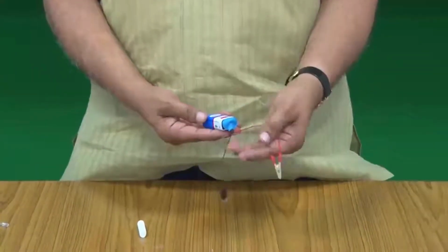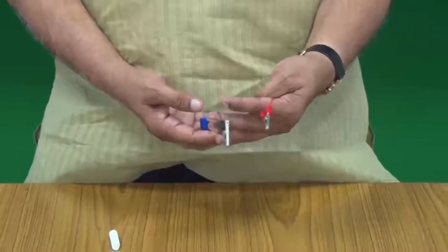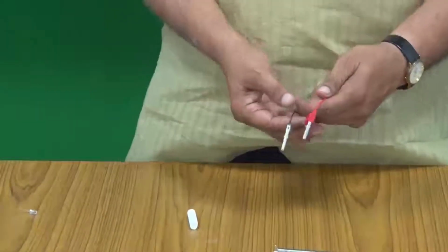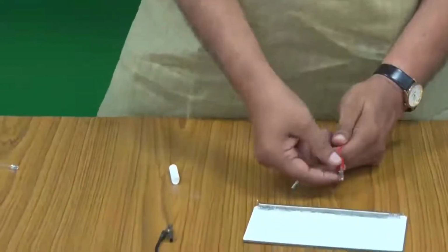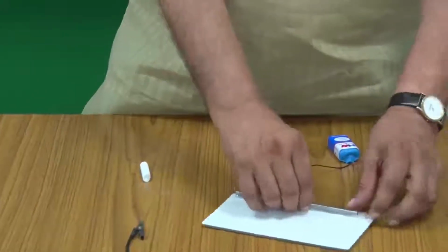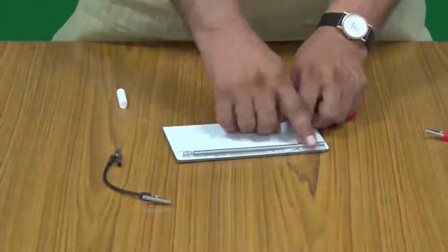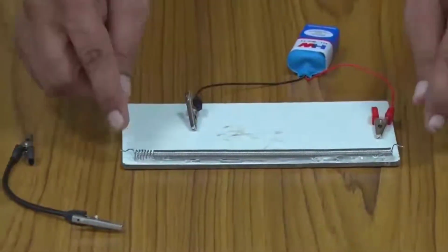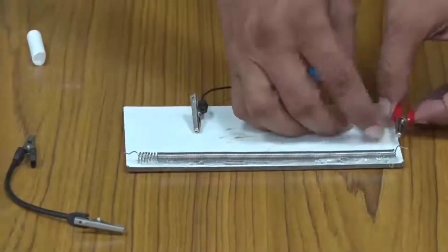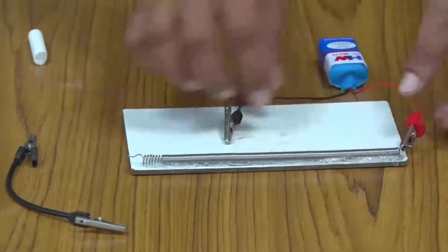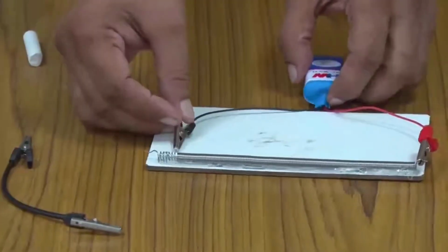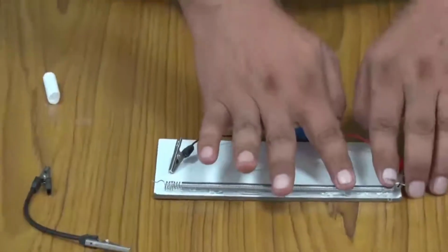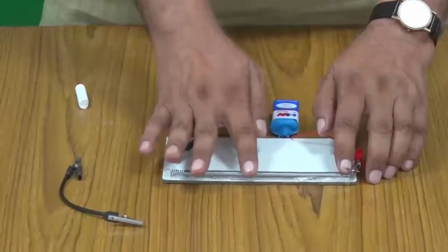I have this 9 volt battery, but I cannot give this 9 volts to the LED, it will just blow. I will talk about that a little bit. So, what I am doing is I have taken this wire, this is a heater coil, and I will connect this battery at the ends of these two wires. One I am connecting now and one I will connect when needed. So, this will go here. The whole 9 volts is dropped across this, and then I can take part of it, smaller voltages, from here.